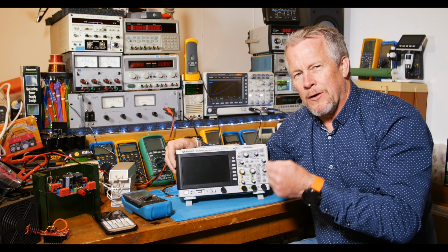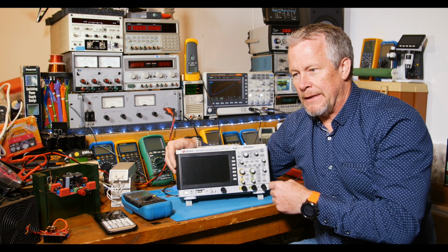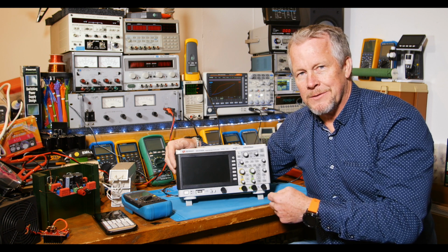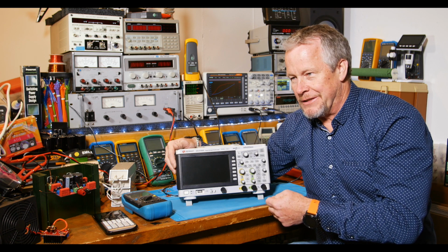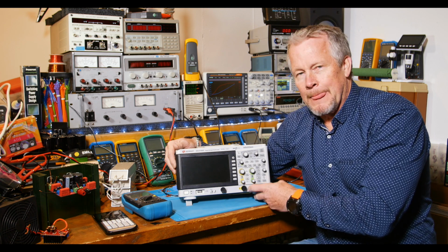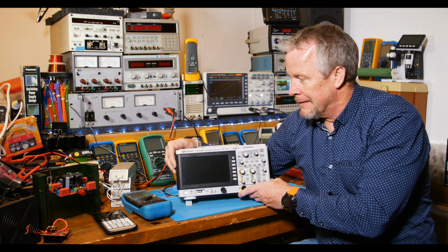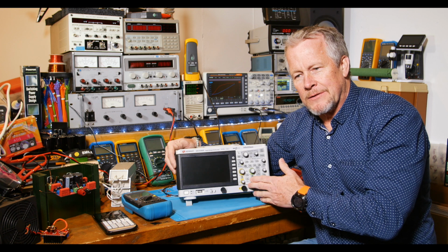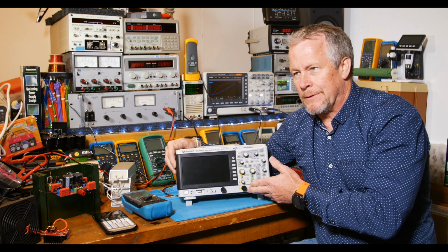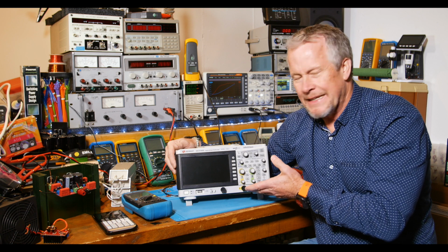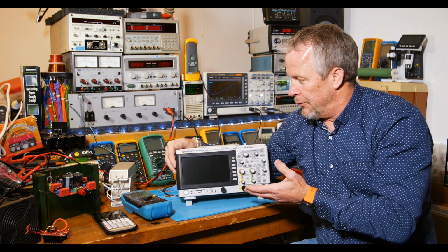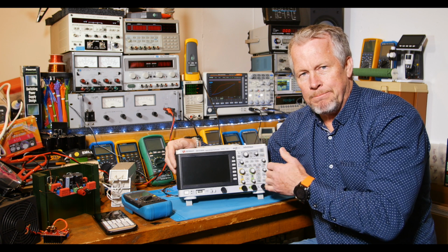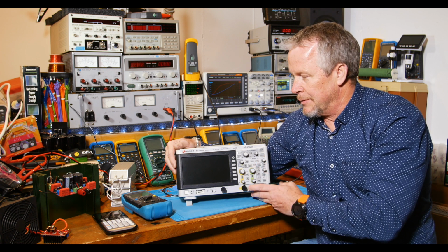Well, but there's also interwinding capacitance, the capacitance between windings. Well, yeah, I can measure that, and I can go ahead and put that in my math. Wow, you're kind of challenging yourself, I guess. I mean, hey, that could be fun, but that interwinding capacitance, is that evenly distributed? How does that change with the core material? There's just a lot of things, and when you can do a Bode plot across a frequency band of interest, then that's really useful.